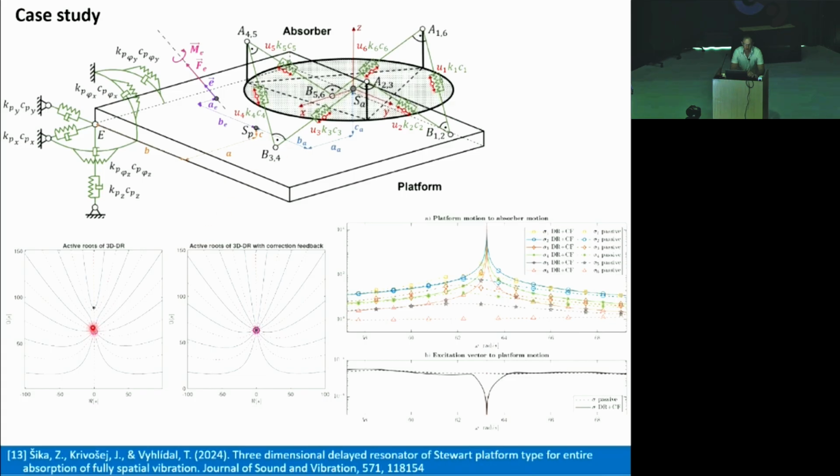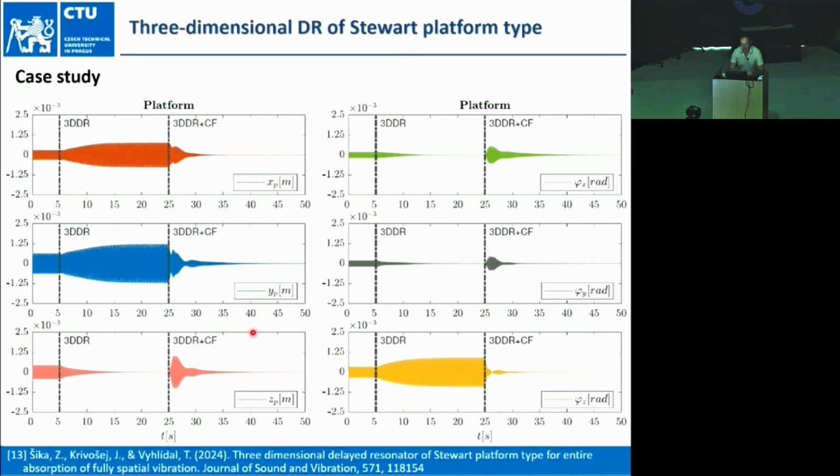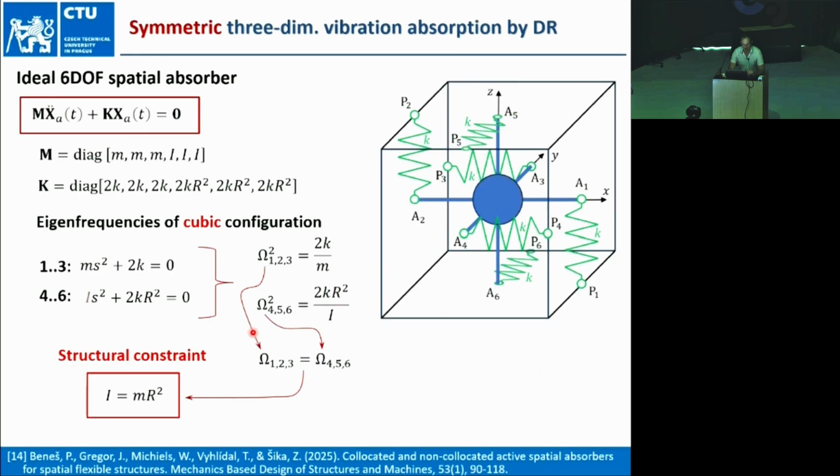After using only the time delay feedback, we can place five eigenvalues to the excitation frequency, but one is aside, and this pole needs to be placed here by additional torsional feedback. So at the end we have the ideal behavior. Okay, so it works in simulation. And in that cubic configuration, it is much more convenient. So it can be done perfectly. The results are straightforward.